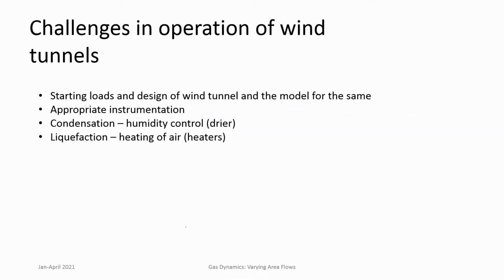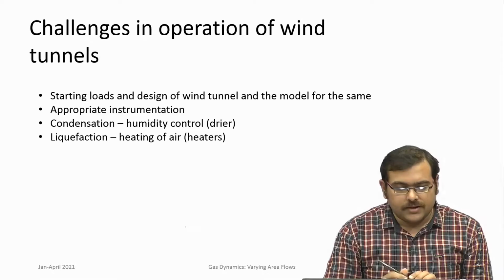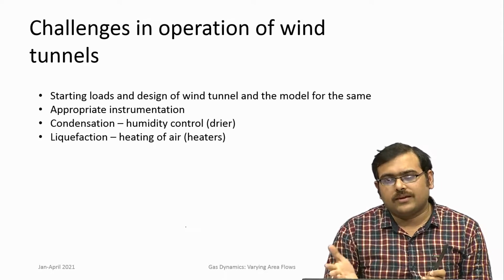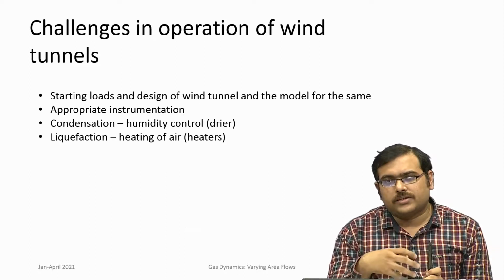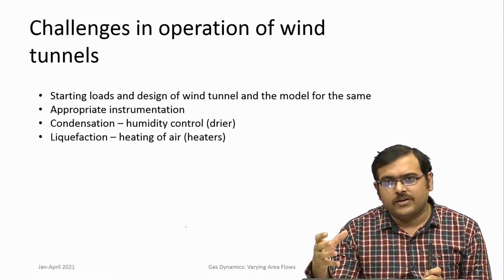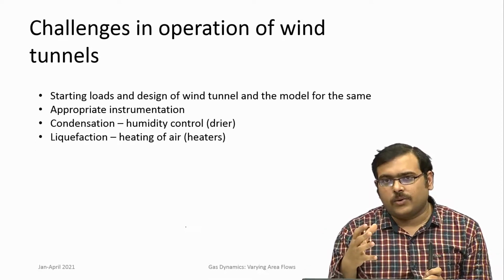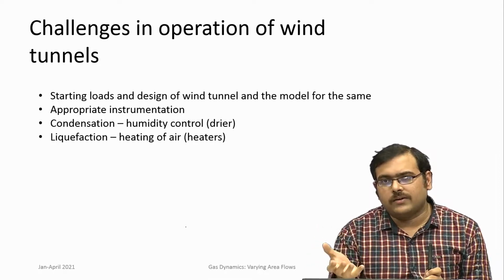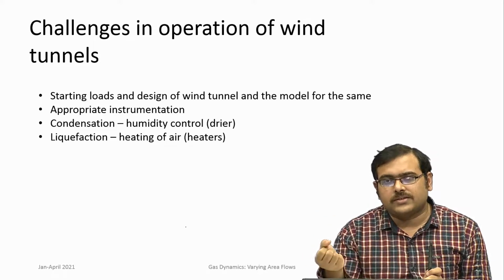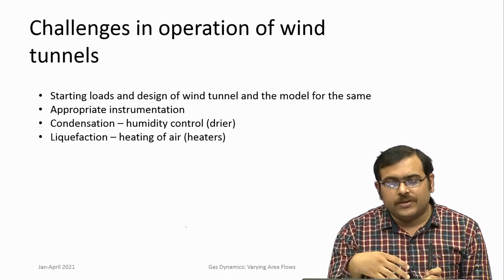Okay. Besides these points, there are other challenges also in wind tunnels. One is, now we know that you have to design for starting. That means initially you have to give much higher pressure, so that the nozzle starts, the diffuser starts, and the wind tunnel operates. That is known as a starting load. The starting load that you have to give, or starting pressures that you have to give to the wind tunnel so that it achieves starting, is quite high.